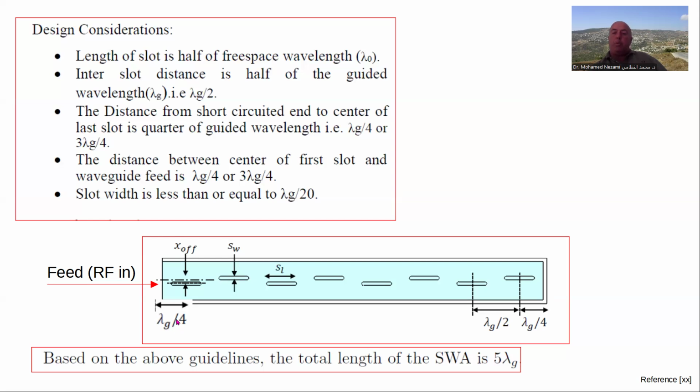Now, this doesn't have to be exactly a quarter wavelength, because a lot of times you cannot use a quarter wavelength, since the length of the slot will come outside. So really, it's an odd multiple of quarter wavelengths. You've got 3 quarter wavelengths, 5 quarter wavelengths, 7 quarter wavelengths, whatever you need. In the example I'm going to show you today, I use 3/4 of a wavelength.